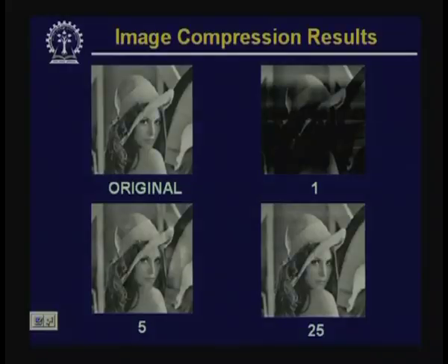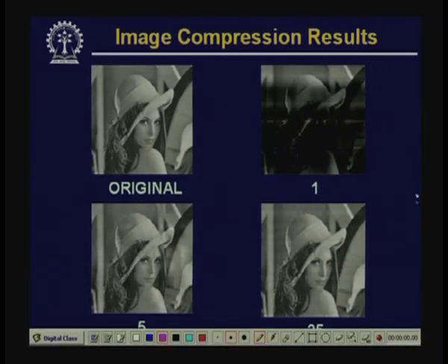In the earlier result that we have shown, using only one eigenvector as the transformation matrix, I can still reconstruct the image and say what the content of that image is, though the reconstruction quality is very poor. That shows that the energy compaction in the number of components is much higher in the case of KL transform than in the case of other transformations.